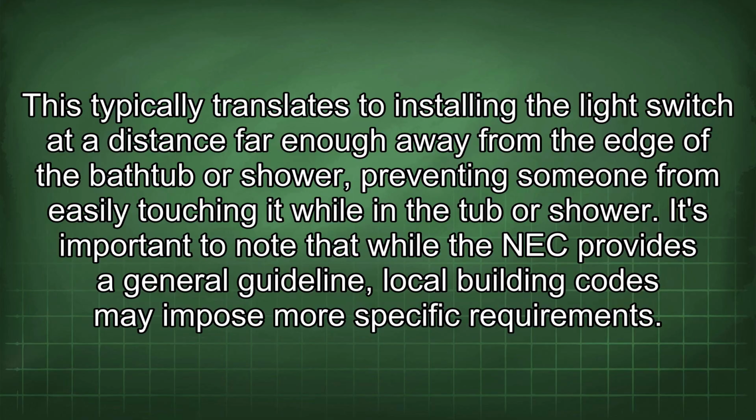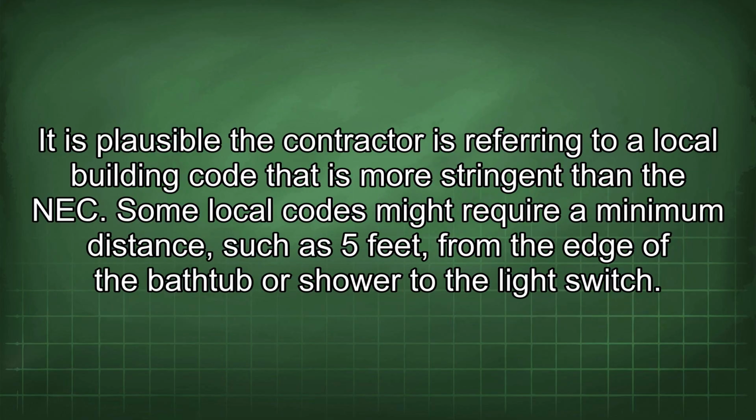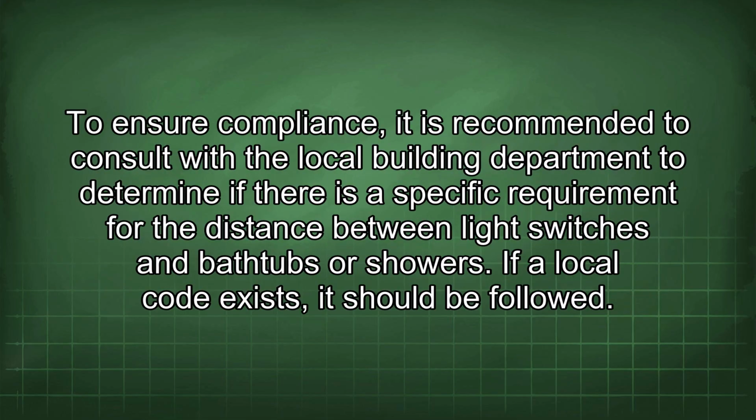It's important to note that while the NEC provides a general guideline, local building codes may impose more specific requirements. It is plausible the contractor is referring to a local building code that is more stringent than the NEC. Some local codes might require a minimum distance, such as 5 feet, from the edge of the bathtub or shower to the light switch.